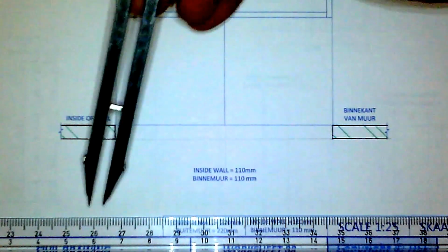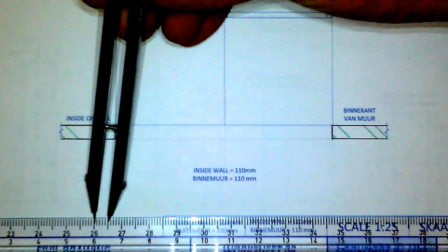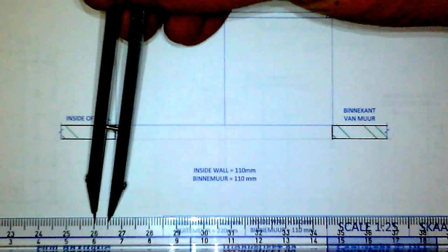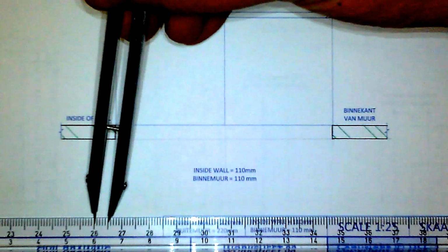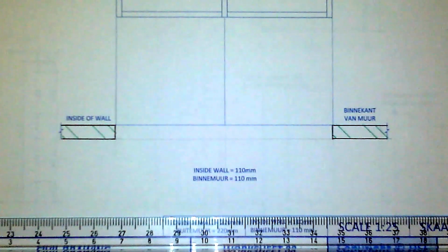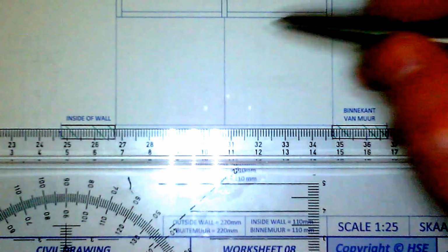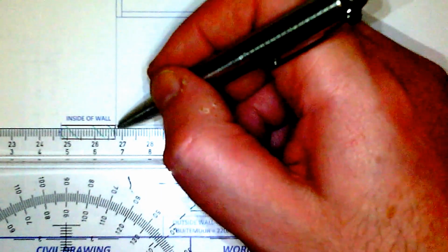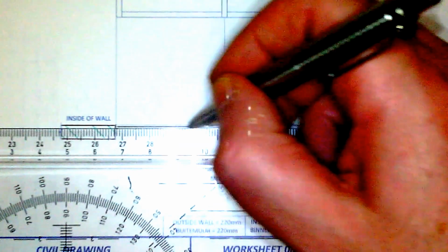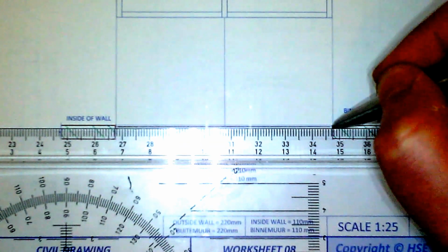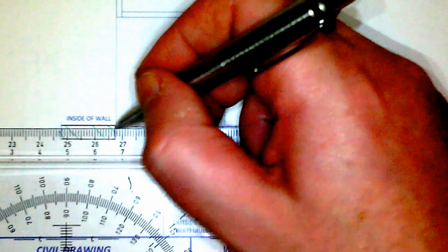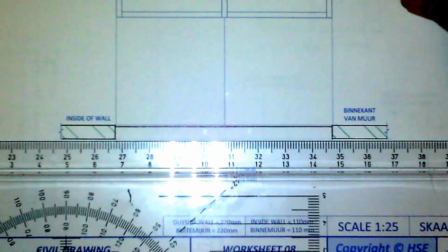If I compare that on my ruler, you'll see it's actually 5, and they've already told us that the sliding door should only be 4. So I'm going to carry that 4 over, so it will have slightly less thickness. Okay, and all you have to do there, you're going to leave this line, and then 0.5 millimeter out, you're going to draw the first line for your sliding door, and then do the same at the bottom.